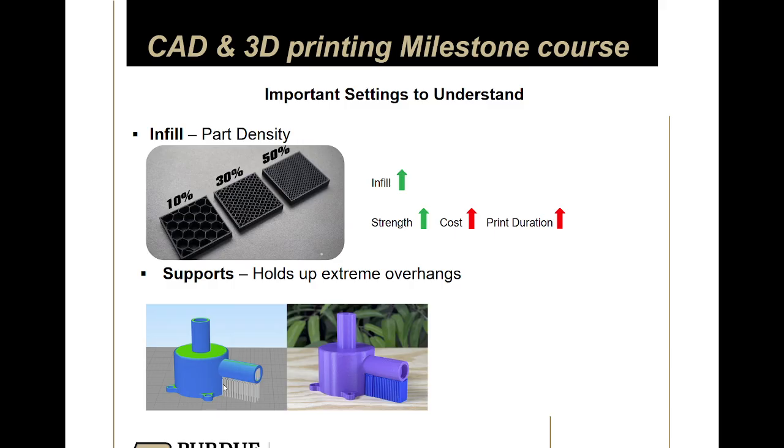So if you tried to 3D print this without supports, this area would just droop, right? Because the nozzle's hot, the plastic is molten when it comes out, so you need something underneath to support it. That's why it's called supports. It's a sacrificial material that people use to make their parts work the way they need to.